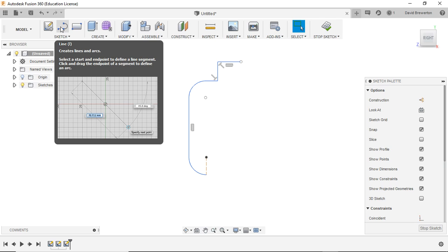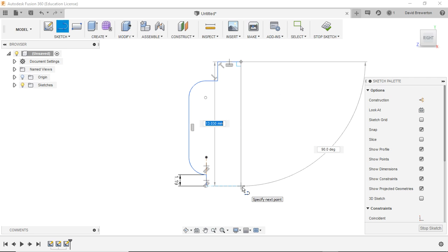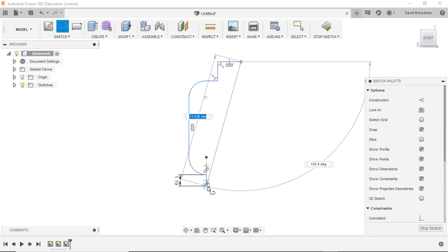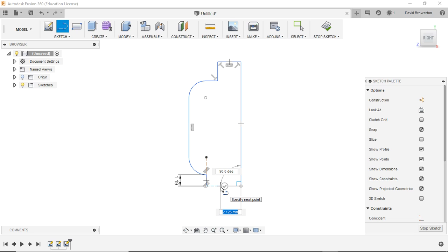What we're going to do now is create a height for the base of that. So we do know that it is 1.19 down. So we know then that from there up to that top is the full height of what we're going to create. So we're just going to create a line from here down to the base. And to make sure that it lines up, we just move across, snap to it, and then bring it back, and it will automatically snap to the correct height that we want. Now across the base of the leg here, just 3.26.